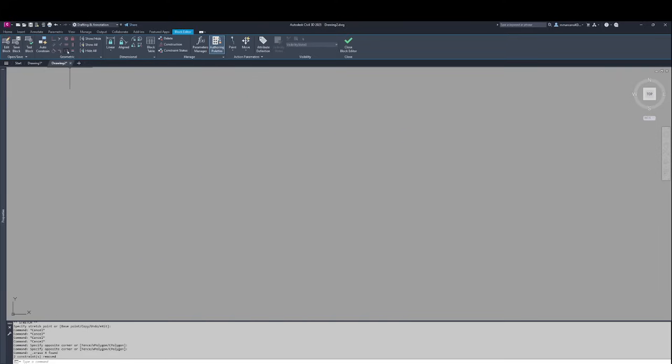All right, so next is what is called our symmetric constraint, okay? Our symmetric constraint constrains two curves or points on an object to maintain symmetry about a selected line, okay? For this, I'm going to have to use 3 lines.